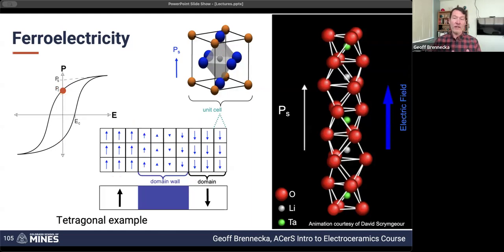But what happens is now we can apply an electric field, and essentially, if we're applying a field that biases this domain, so we're enhancing the polarization of that domain, then we're going to essentially shift this domain wall to the right, and if we encourage the polarization domains that are pointing up, then the way that those domains grow is by this wall shifting just a little bit and essentially consuming the domains that are of the opposite polarity.